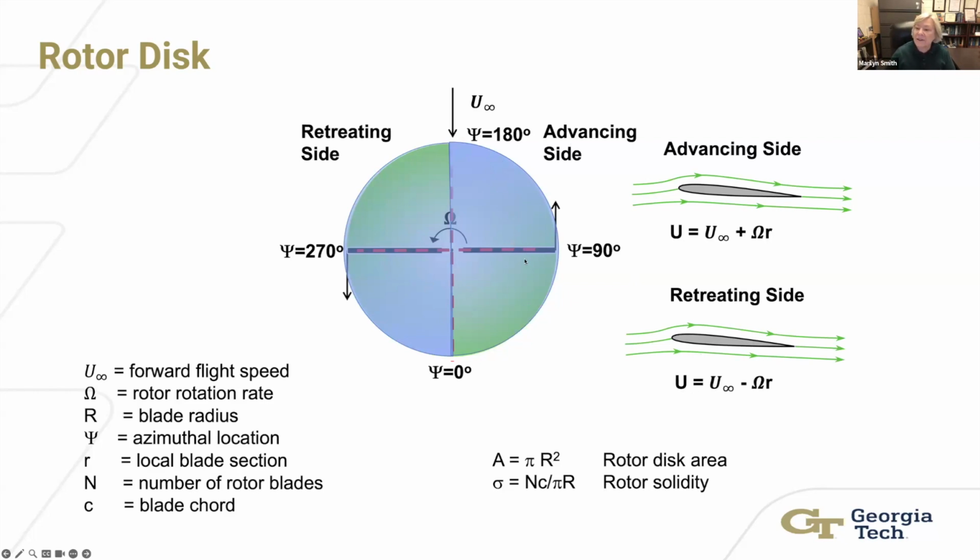On this advancing side, you're going to be at small angles because you can generate higher lift with those higher velocities. On the retreating side, however, you have lower velocity. That means, of course, you're going to have to pitch your airfoil up, or your rotor blade up. So higher angles of attack, and this is where you can get into stall considerations.